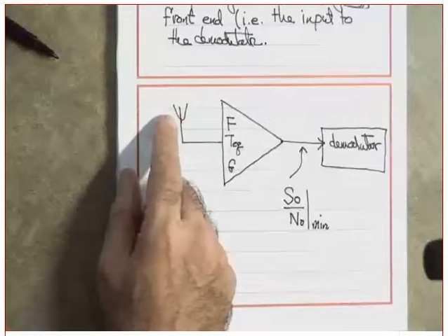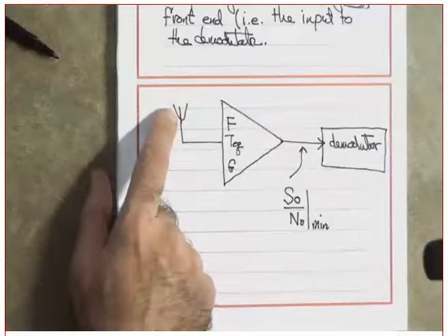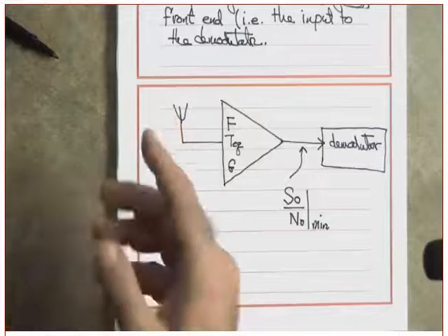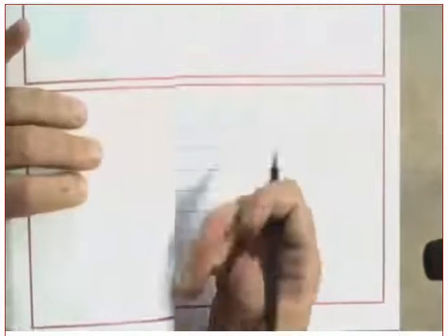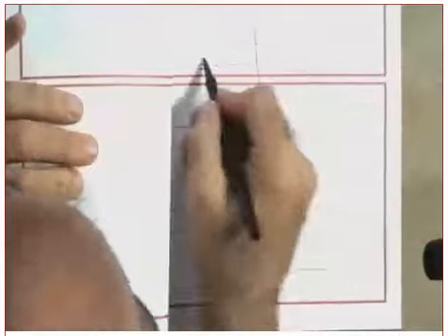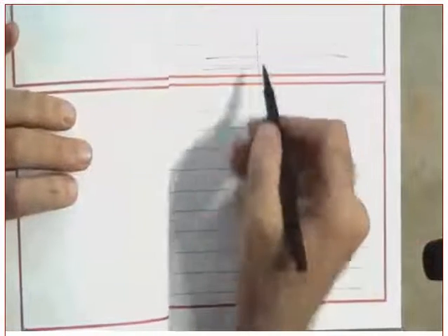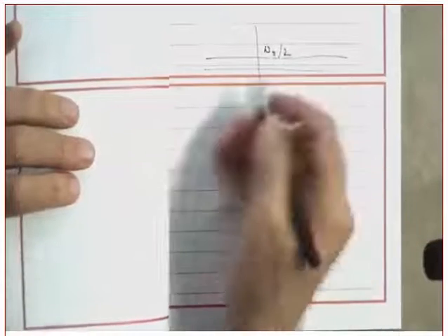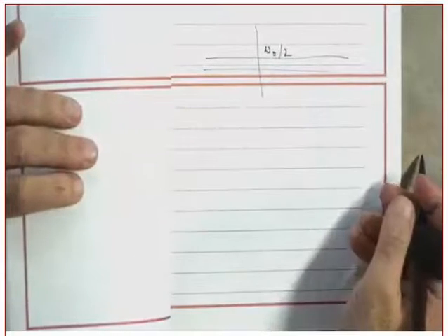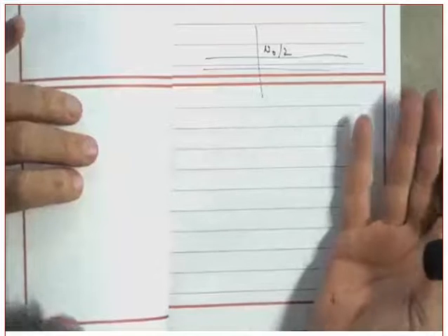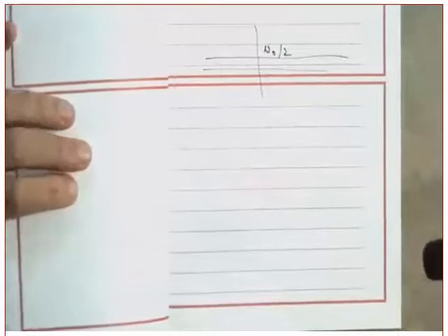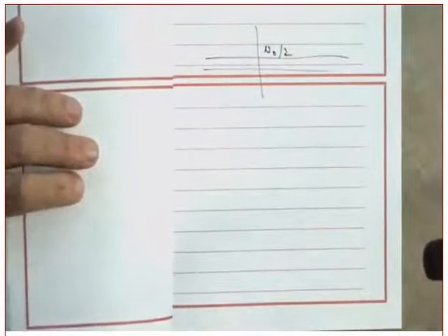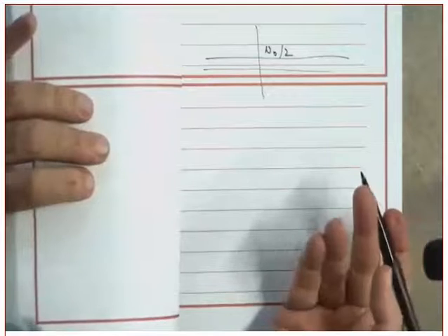By the way, what is the signal to noise ratio? Can you tell me what the noise power is here? If it is thermal noise, the white noise, what did we say? N0 over 2. What is the power? The noise power is the area under the curve, which is equal to infinity. It means that no matter how strong your signal, the noise will eat it alive.